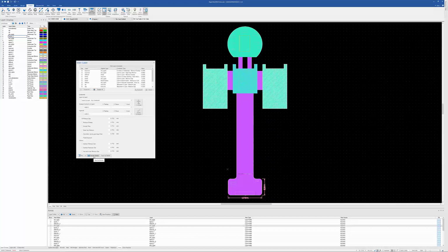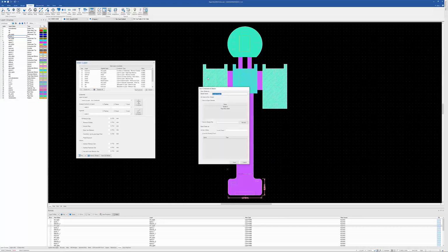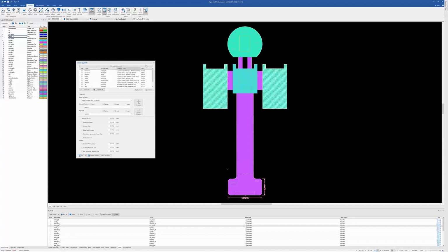If those of you that are familiar with our checklist, it is layer-based typically, but what we can do is we can add these interlayer checks to that stream, and we can create a new stream or a new checklist, or save it to one we have open. And I'm just going to save it to our default one here, and you can rename it as well if you want to.